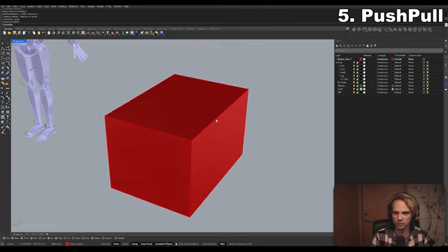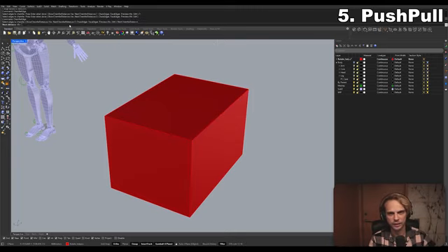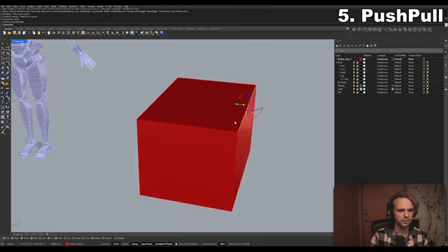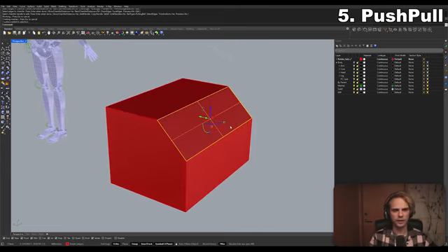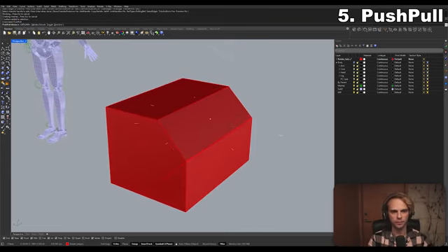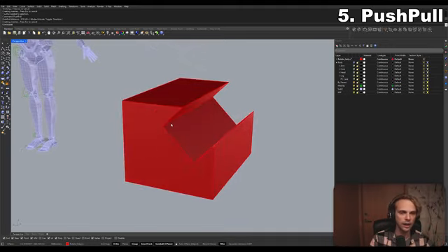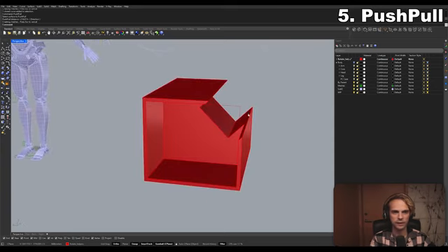Let me show you a different thing. So for instance, if I have this edge right here and I chamfer it, chamfer edge, and I give it, sorry, I first need to say the next chamfer distance is going to be, let's go for 50, something large-ish, right? Actually more, apologies. Chamfer distance 250. There we go. And I can, of course, push-pull on this, push-pull inwards, like that. And it does all the Boolean operations, everything that I needed to do by itself. And I can still, this is, remember, the curve? I can still repeat the push-pull command, select the inner surface right here, and push-pull on it like that. As easy as it gets.